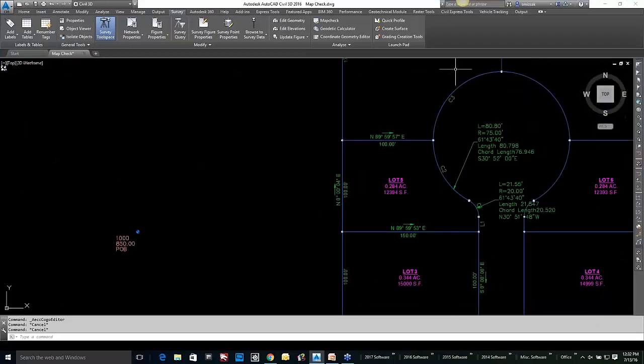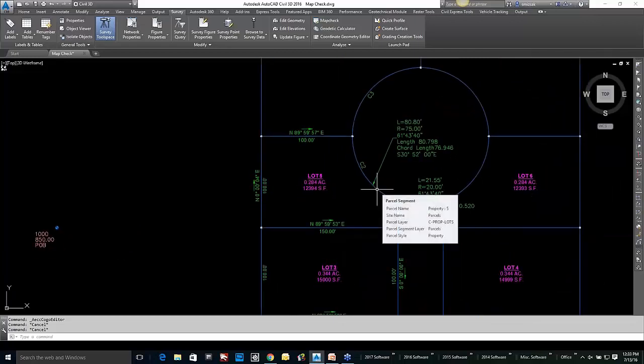So I guess trust me on the demo that if you plug those in the right order, things will work. What I'll do is I'll quickly talk about going through there. The C2 I actually put in as a radial curve. So I plugged in 180 degrees because I was coming straight out, and then the 75-foot radius, and I put in the delta of 61 degrees, 43 minutes, 40 seconds to get me to here.